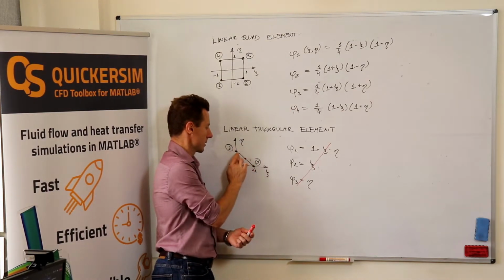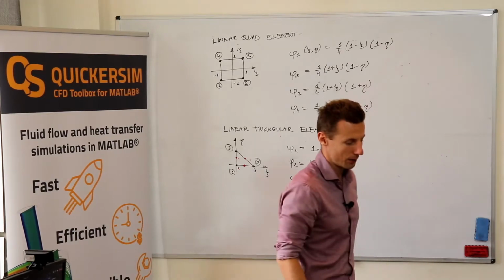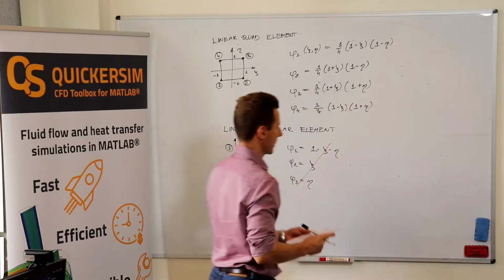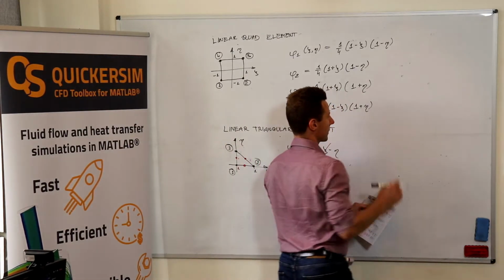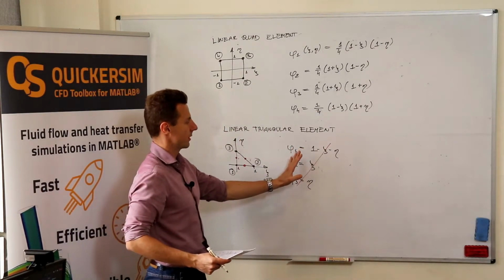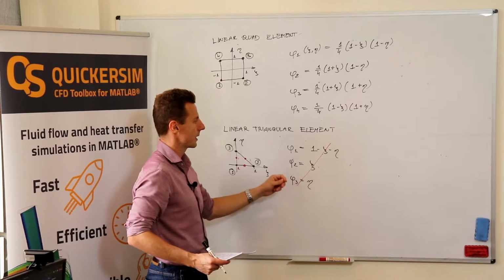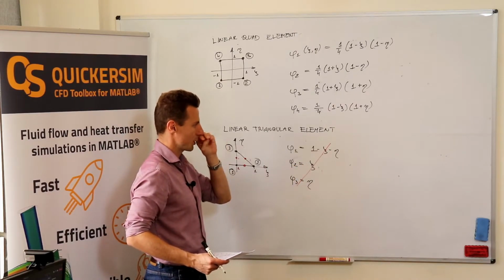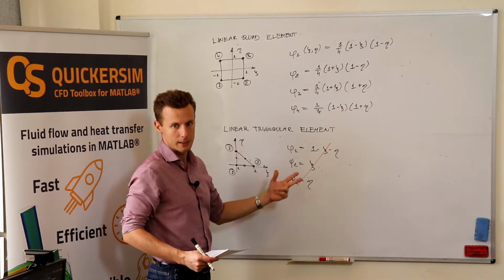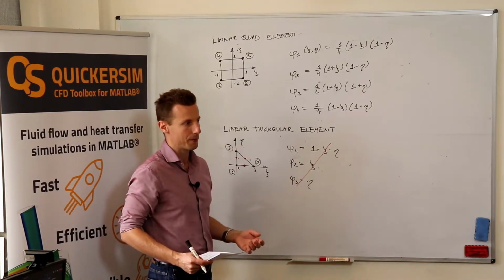And now, something that Konrad wanted me to show is how do you basically come up with the shape functions or test functions that you are using. The idea is the following: we don't want to have a linear element anymore. Right now, we are interested in having a second order element. So what would we add? We would additionally add xi squared, xi times eta, and eta squared. These are all the combinations that you can come up with if you want to extend the functions to the second order.